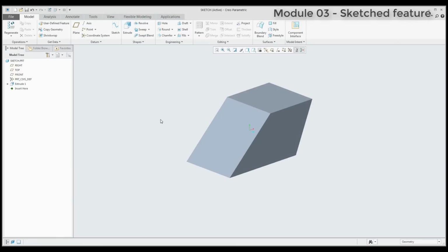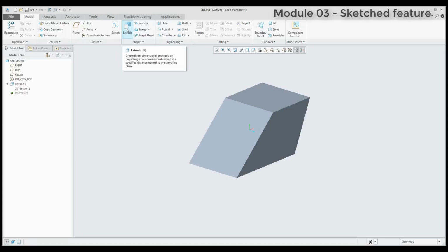If you are working with 3D models, many times you have to specify, for example, the extrude feature, revolve feature, or another type of feature, and inside of this feature it is necessary to define the section. Or you can select the sketch feature and directly create 2D curves. I'd like to focus on the sketch functions, and for better explanation, I will create another extrude feature.